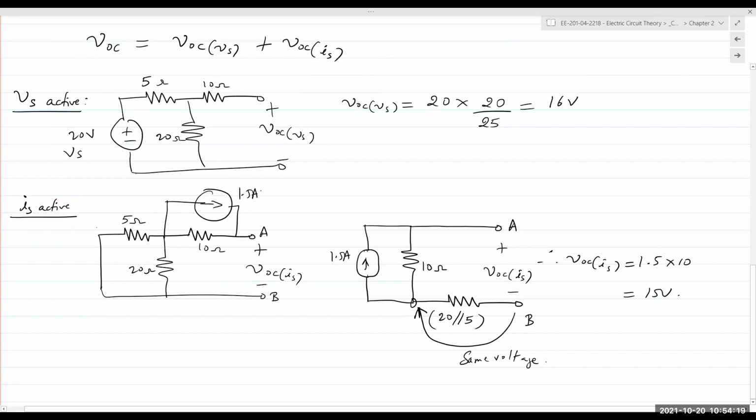Does that make sense? All I'm doing is combining this and just drawing it a little bit differently so it makes sense, right? Two in parallel, there's no pathway for the current to flow through, so there is no voltage drop across here. All of the voltage is across 10 ohms. The polarity works itself out because the current source is flowing towards the right, upwards direction. It's coming from the top. That means this is plus, this is minus, matches up with our assumed polarity of VOC.